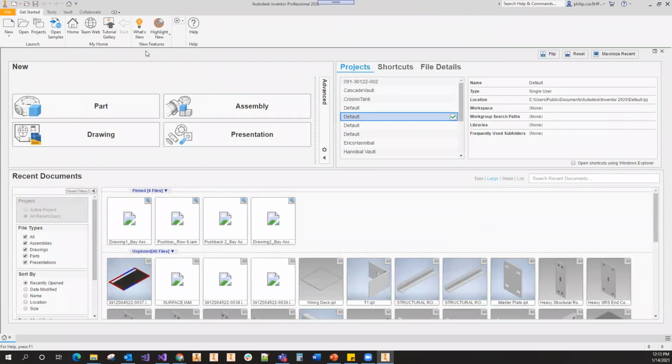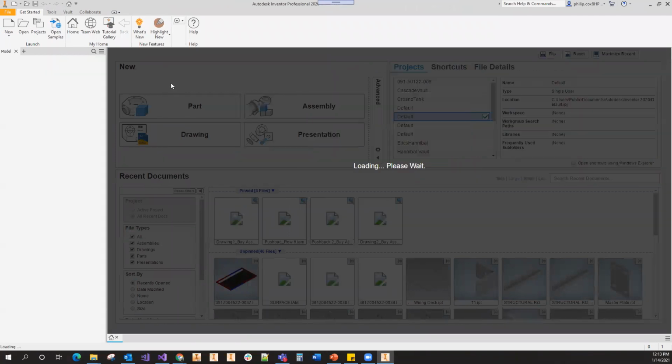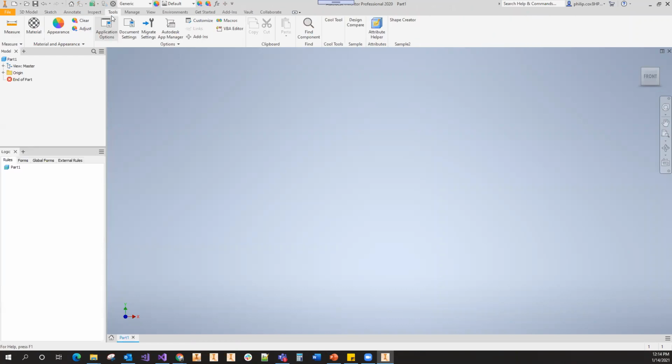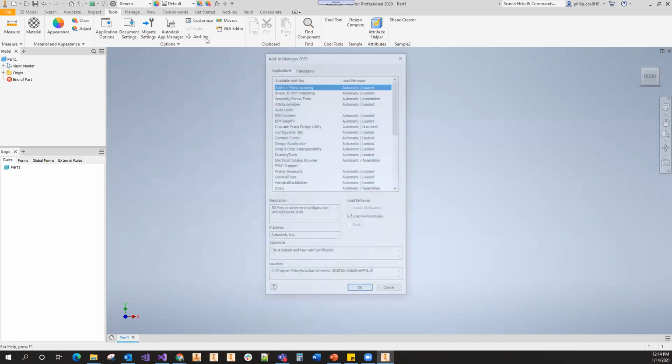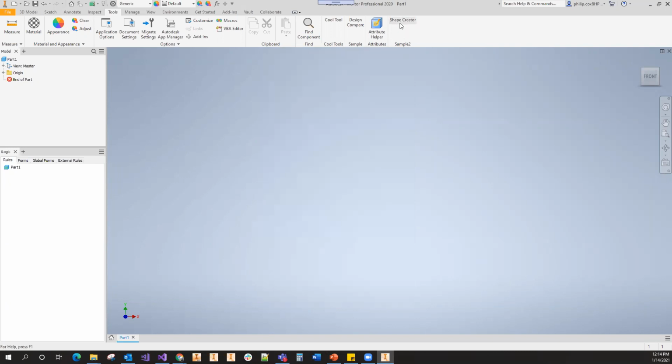Now we chose to put our button in the part tools ribbon. So I'm going to go into part, come down here to tools. Just as a refresher, if you're having trouble finding your add-in, ours is right here. Go into add-ins and it might be blocked. Okay, go find your add-in, this is demo. It's not blocked. Cool, it's working. But here we can go ahead and click this and boom, we get our form. We've launched our first form.